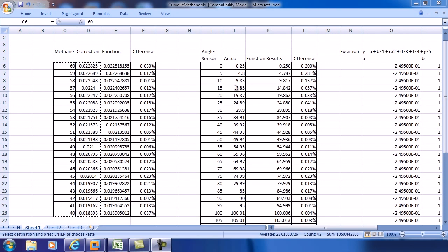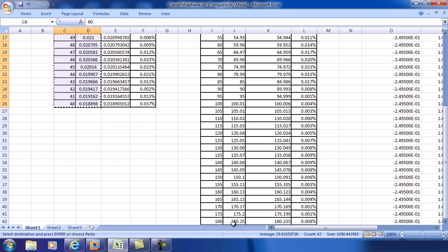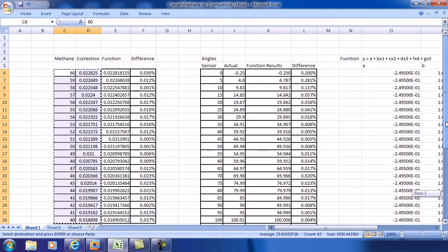Same thing over here. We can see that when the solar collector is flat, there's maximum displacement, or a difference, at the receiver. This is once again the pipe that flows the heat transfer fluid. Due to gravitational torque on the receiver as it hangs out, we can see it has maximum displacement from the angle sensor at its two extremes of movement, the 180 and the 0. And we can then see over here the percent difference that I'm actually getting based on my function.